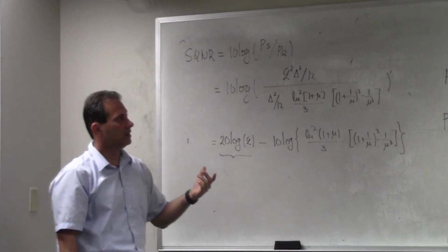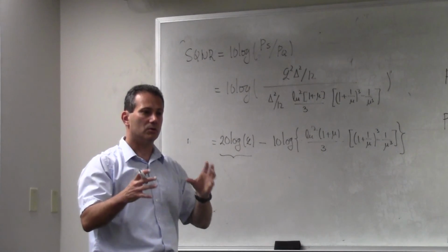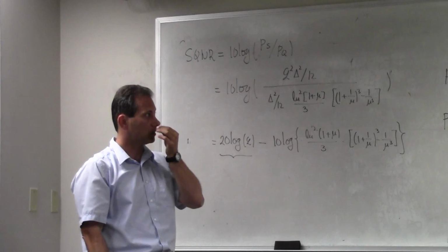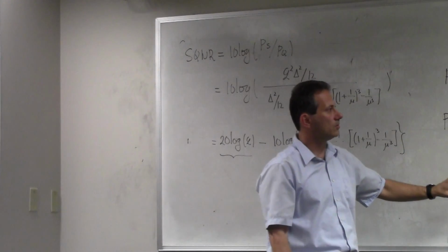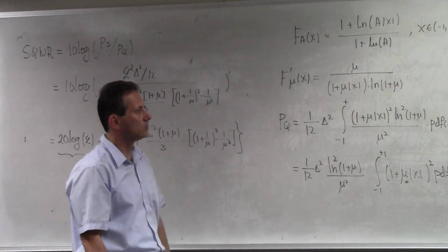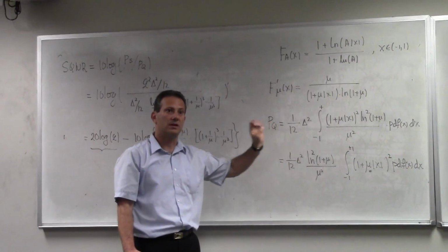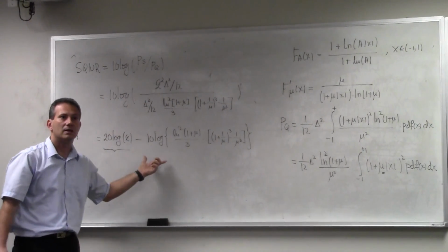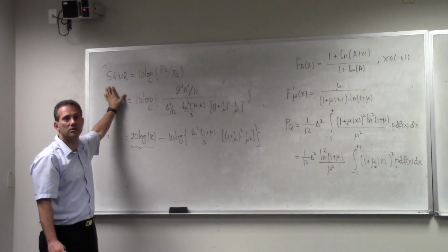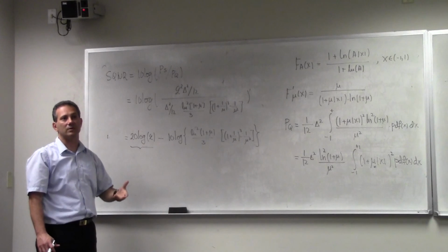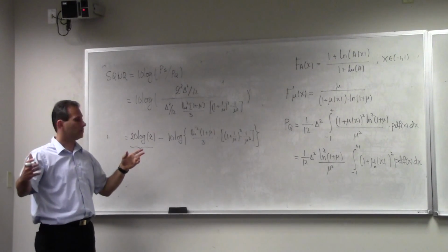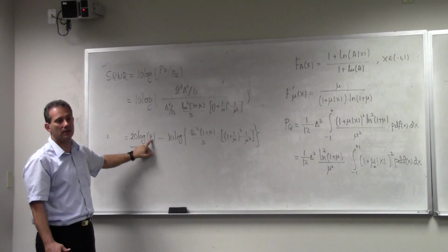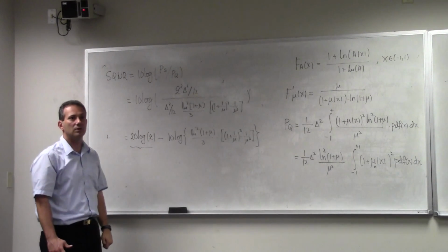And in practice, you're always going to be dealing with a uniform quantizer, and then a lot of times you have circuitry up front that performs the compression. This allows you to understand what kind of compression you need to apply and what the penalties in your signal to quantization noise ratio are if you know the PDF of your signal and the amount of compression. By choosing a proper compression, you can gain in signal to quantization noise ratio. Now, you can trade that gain for bandwidth, because if this is larger than what you need for a given signal, then you can operate on Q and get a smaller number of bits that you need for a given quantizer.